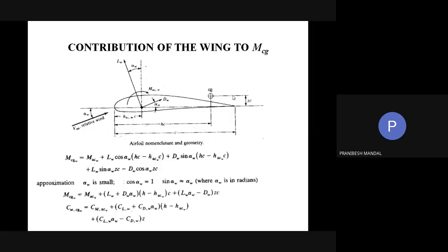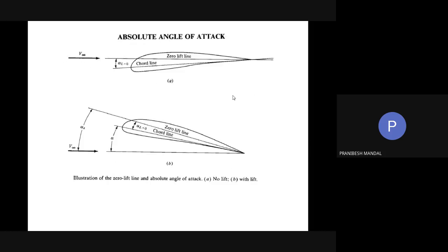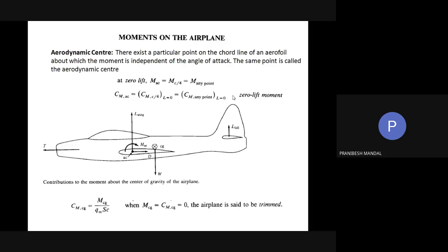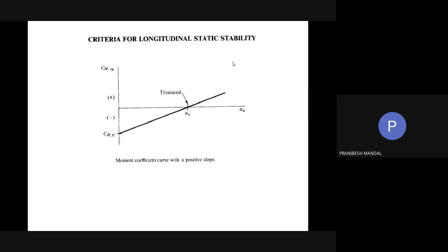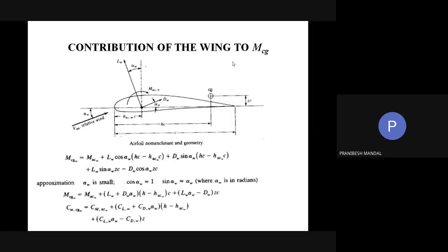First of all, consider the wing, only the wing. I am showing you the total figure again. This is the total figure, and of this particular thing, consider the wing only. So if you consider the wing only, then for the wing only, there are lift of wing, drag of wing, and the moment about aerodynamic center of wing. These three force moment combinations are there. Yes or no?